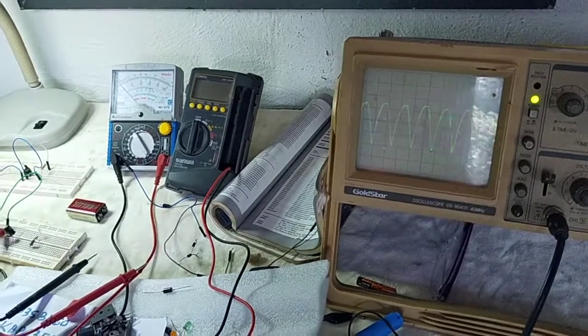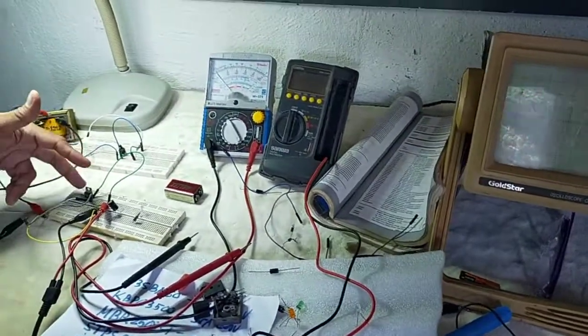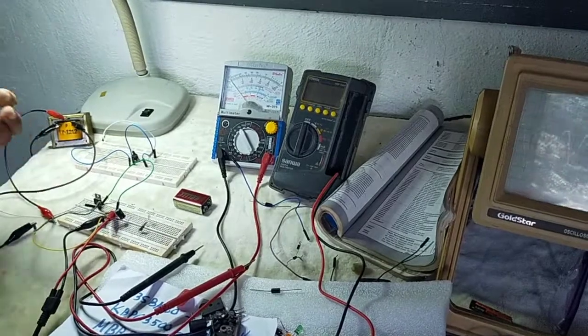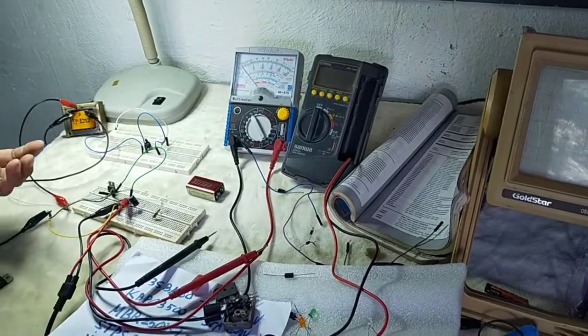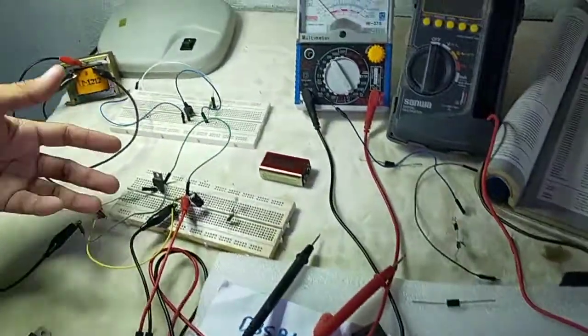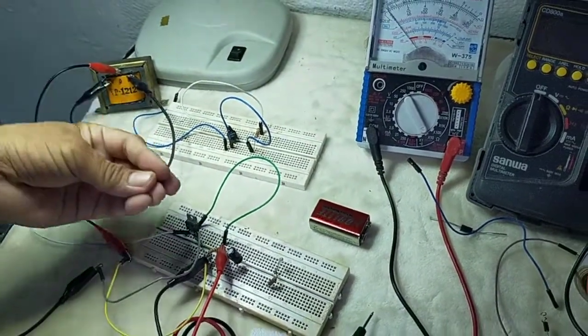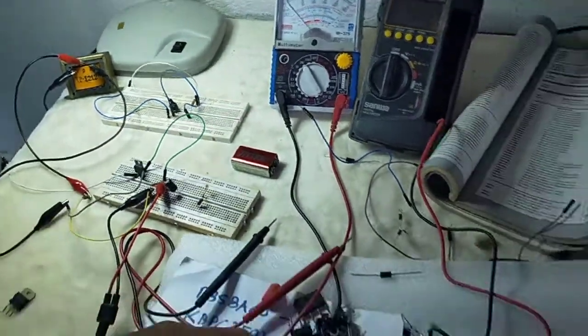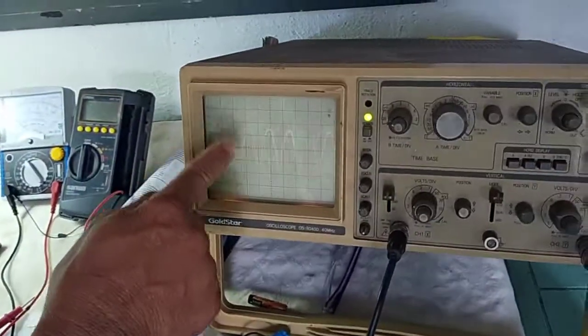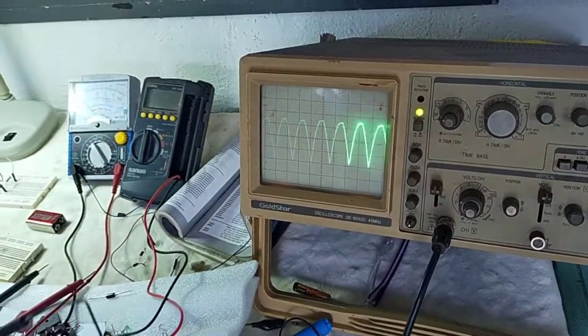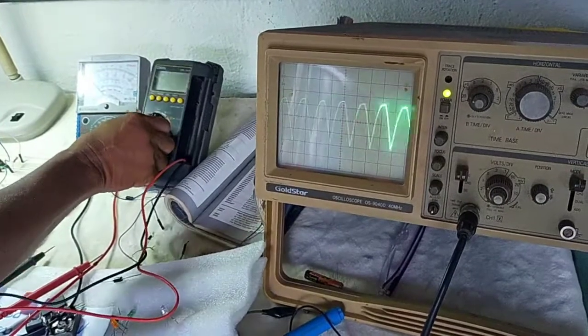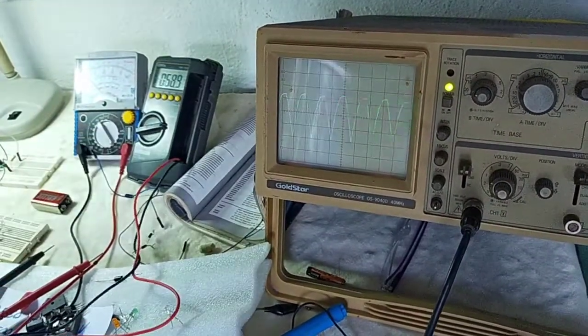Here's the result. When we are using a dual rectifier diode that serves as a full wave rectifier, we are actually using two diodes, but encapsulated into one. So, the output goes like this. It is full wave. And let us try to measure the frequency here.